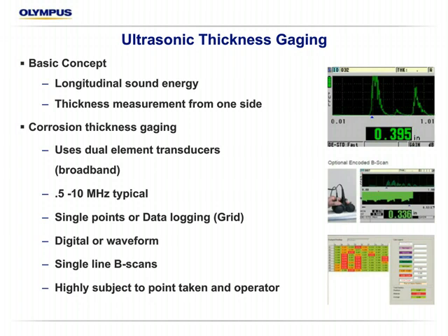But really, a thickness gauge is subject to the point taken by the operator, and there's a few industries right now that are discussing some concern about that. Obviously, if you're given a point to take and that point is difficult to take, it's human nature just to move over a little bit and take another point. So is the sampling really random, and is it really left to the operators? We better have good operators. So there's the general concept.